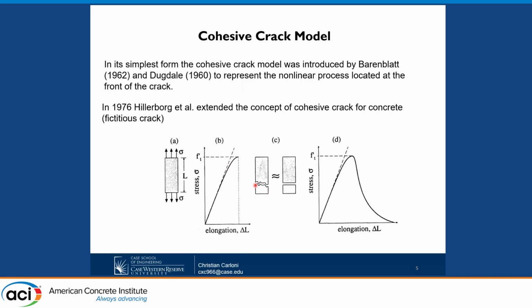So after you reach a crack, you can continue to pull. And what is going to happen is that as you pull more and more, your stress decreases, so you can't carry as much, but you can still carry while opening that crack. And why is that happening? Because there are aggregates that cross the crack, because the crack is not flat, there is friction between the surfaces, because there are voids and the crack needs to go around. So for a lot of phenomena, in reality, there is life after the peak. And we call that the softening behavior of concrete.